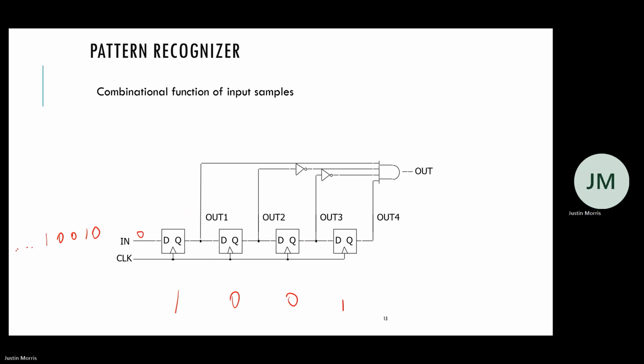First clock cycle, right? We have a 0. So the 0 goes into here. These are all undefined at first, so the output is undefined. Because if I can't determine what this is, it's just X. If I invert X, it's still X. With a 0 AND X AND X, well, we know it will become 0 because of the 0, but let's just continue doing this.